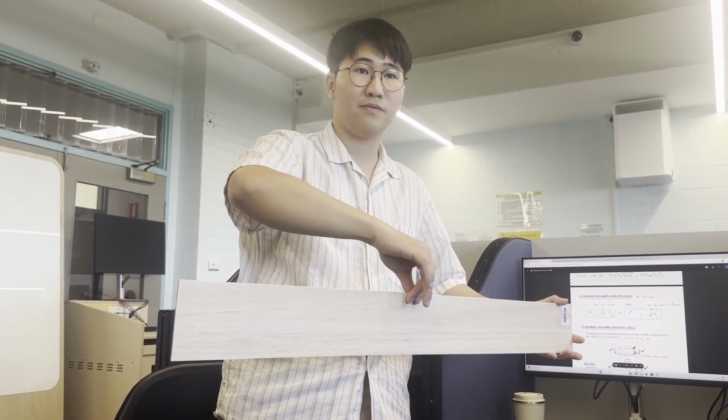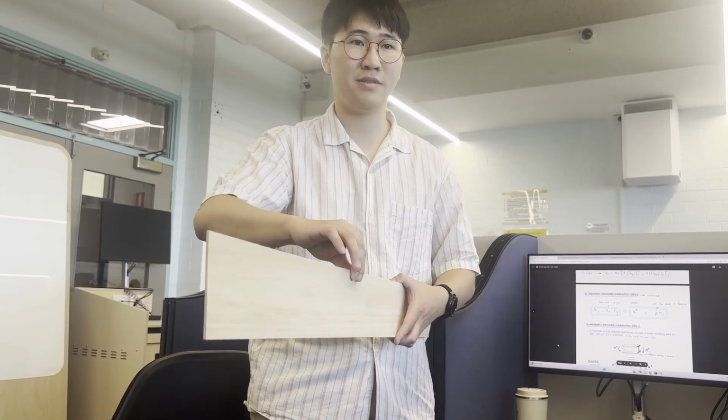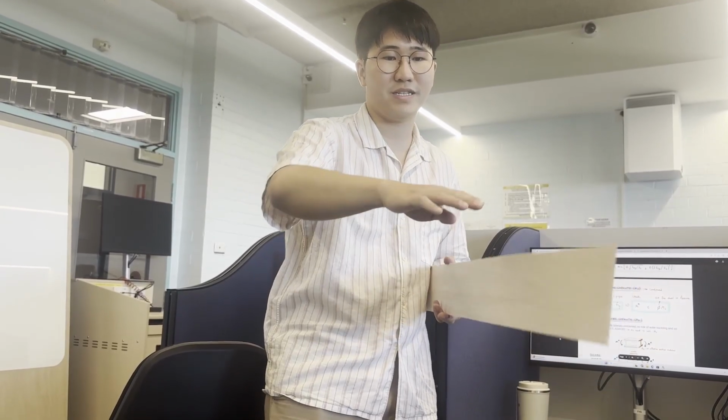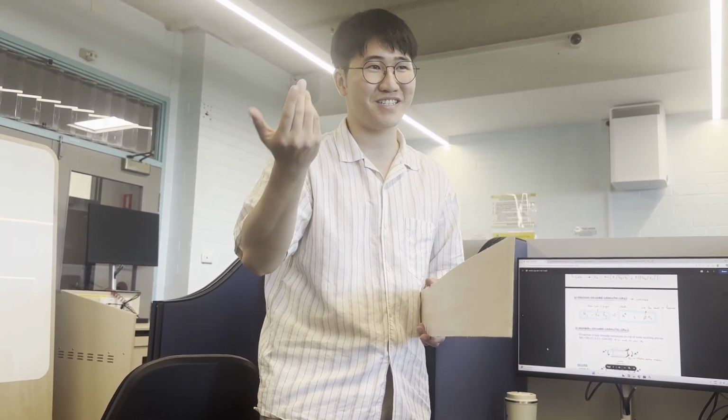Okay. What's weird is that was in compression. Oh, sorry. Yeah, the lateral torsional buckling happened on the compression flange, right? I say flange as if it was an I-beam, but on the compression side for a simply supported beam, which makes a lot of sense, right?